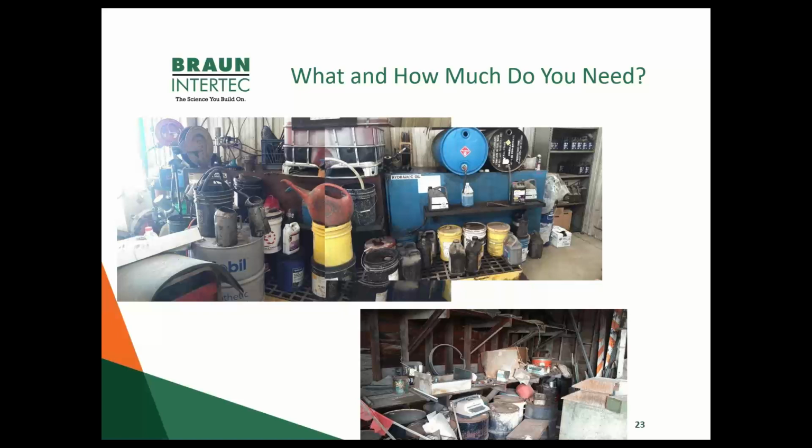A lot of times we may actually be able to help a facility that may be on the cusp of needing an SPCC plan, because like Josh said, you've got maybe dozens of these half-used or unused or no longer used 55-gallon drums on the facility. If we can help folks identify where they don't need to have this anymore and get rid of this, sometimes we can get under that 1,320-gallon threshold, which means that they are then no longer subject to the federal rules, the inspection requirements, the reporting, and you know, can just work on complying with their state regulations. Yep.